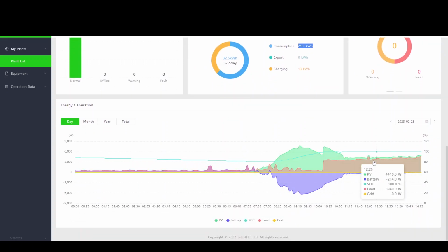This is the most handy part of the diagram here, to see where your loads are at and what's going on where. And you can toggle these on and off if you don't want to see PV, if you don't want to see your battery. You can click those on and off. But you can see here, I know our load's pretty good. So this is just our overnight parasitic loads: fridges, freezers, pumps, softeners, that kind of thing. And this would be when the coffee maker kicked on in the morning. This would be one shower, two showers, and then the solar starts kicking in and charging.